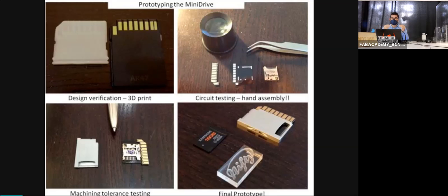If you can assemble your model in the laser cut with just thinner materials, just scaling down the materials, your model will probably be easily assembled in the CNC. It happens a lot. Every year, more or less half of your models fail on the CNC. Why? You didn't think of the assembly sequence. So you try to assemble one part, then the other directional part, and it doesn't fit because it's impossible to assemble.